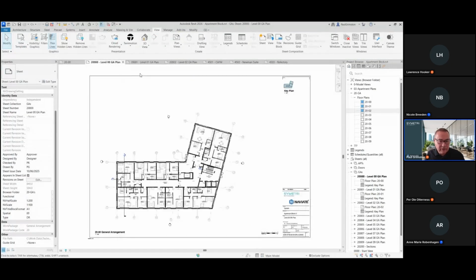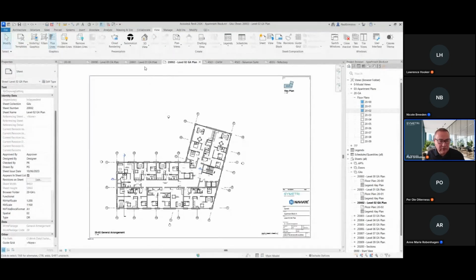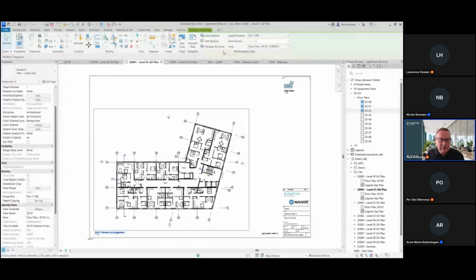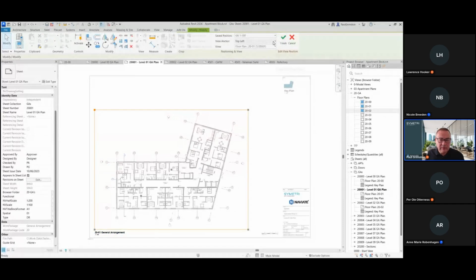And then we can see that all of these views have now been repositioned into that same location. And if we started to place any of the others in, then they're going to drop into this new location as well. So that's kind of the idea behind it. Just seeing the question pop up as I'm looking. I do have a scope box here, but I have also done this without scope boxes. So without a scope box, the view anchor itself would just be the view origin, which would be the internal origin of the model.